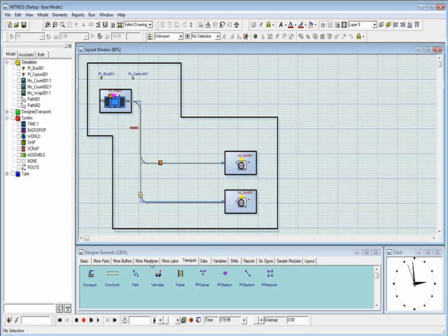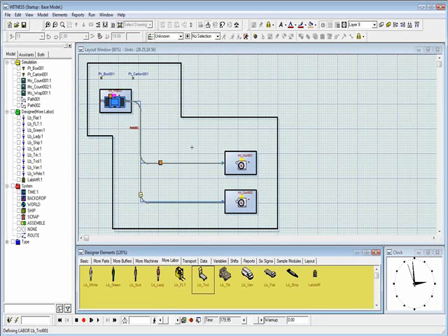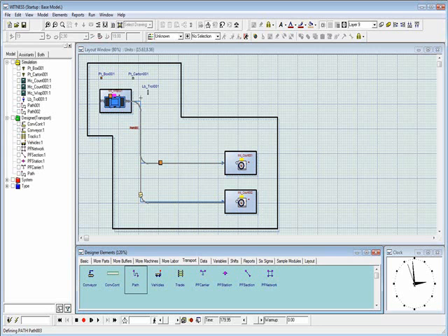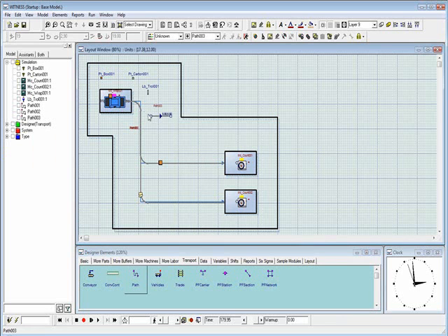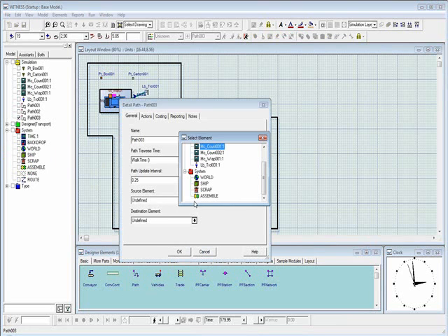The next thing we're going to do is add labour into our model. We want to use a pallet truck to move our parts from the wrapping machine to the counting machine. So just from Design Elements, we've taken a trolley, and in addition to this, because we're going to put our trolley on the path, we need to have a path that moves the trolley from its idle position, its initial resting place, to join the path for the machine. So just quickly define the little path there that goes, as you can see, from the idle to the wrapping machine.